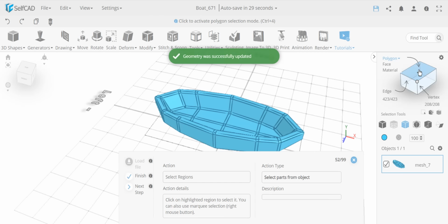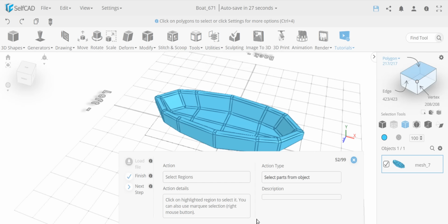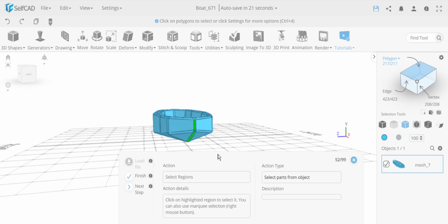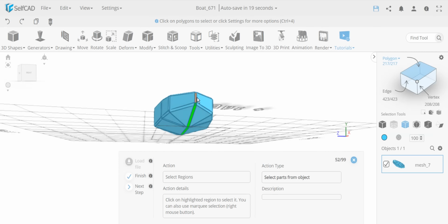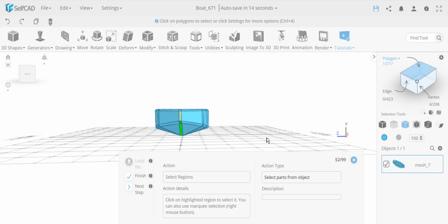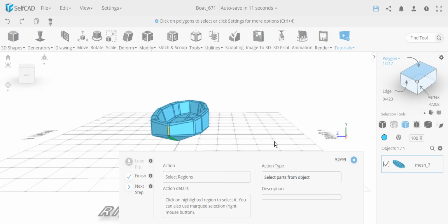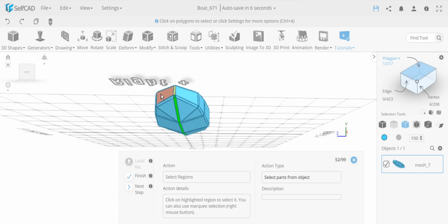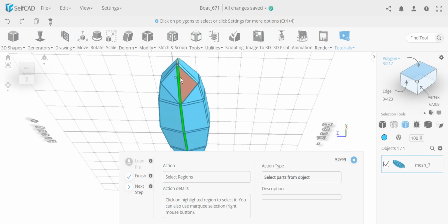Okay, now we go again to polygon selection, and we have to select the highlighted. So what is it? It's just the bottom part and going up over here. So we need to select this. I want to show you a trick idea of my key selection. My key selection could be moved from left to right or right to left. So if I'm going in this direction, left to right, it will select only what is completely inside. Now if you see this direction, none of the faces are completely inside except what needs to be selected. So this wasn't completely inside, it didn't select.